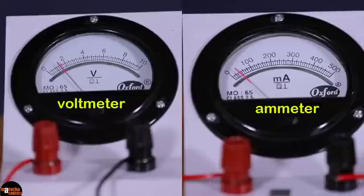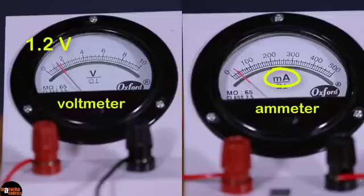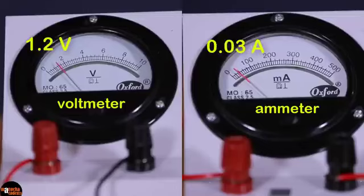As you can see, the potential difference across the wire is now 1.2 volts. And note that this ammeter is marked in milliampere. The reading in the ammeter is 30 milliamperes, which is 0.03 ampere. Note that the wire does not get the full 2 volts from the voltage supply. The potential difference across the wire is 1.2 volts.